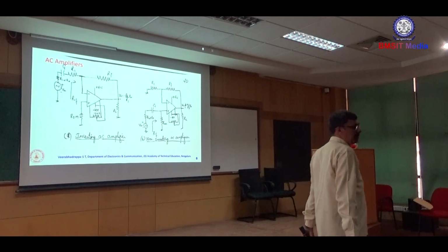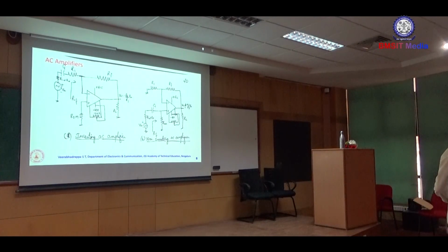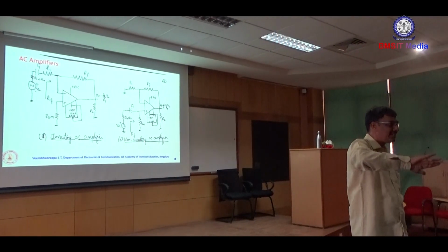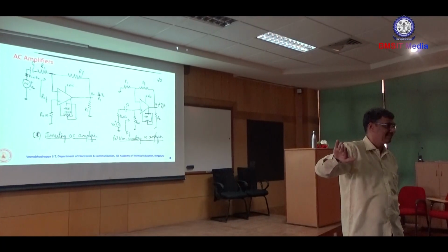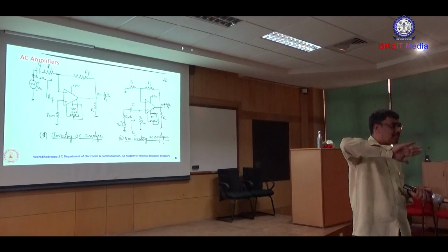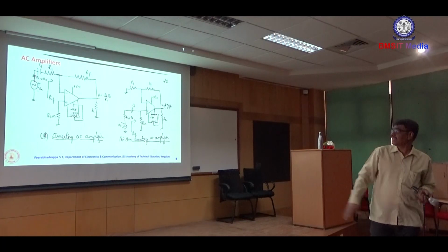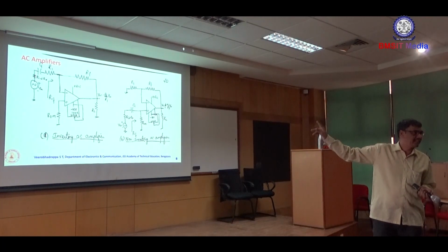Okay, what is the reactance of a capacitor at DC voltage? Very high. It is infinity. Ideally it is infinity, but practically it is not infinity. We always have to say that as a limit the frequency approaches 0, the reactance of a capacitor approaches infinity. It is approaching, meaning it is very high, it is not completely open. Still there is some conductivity. Therefore we always use the limit: even under DC conditions that reactance is very high.